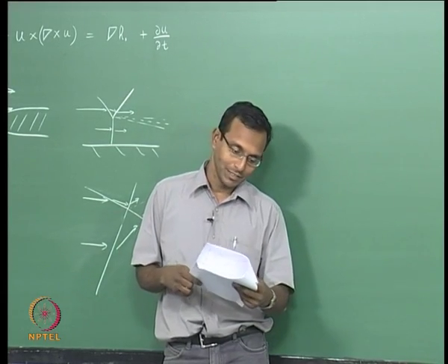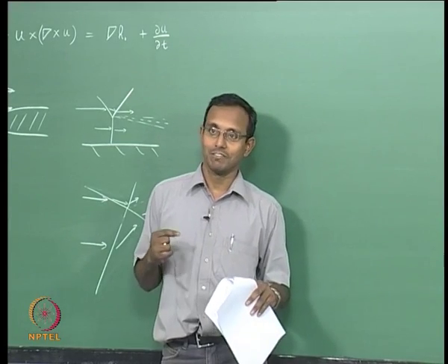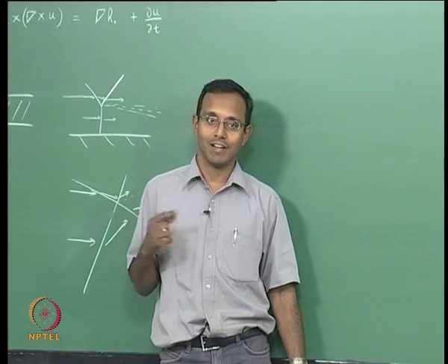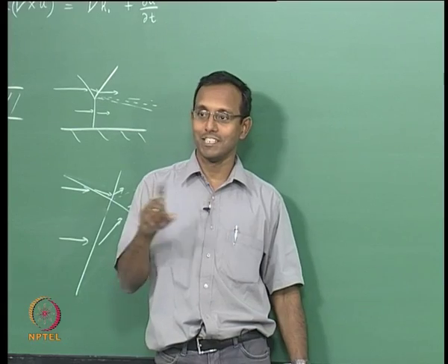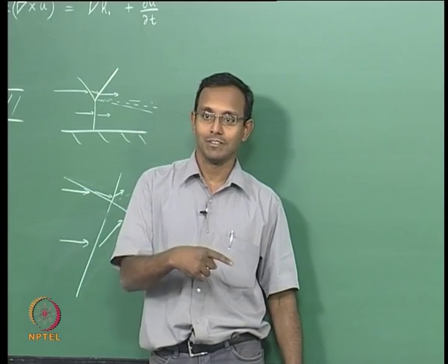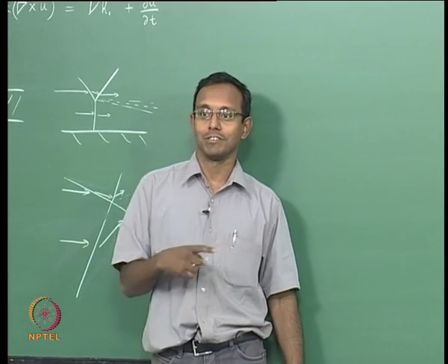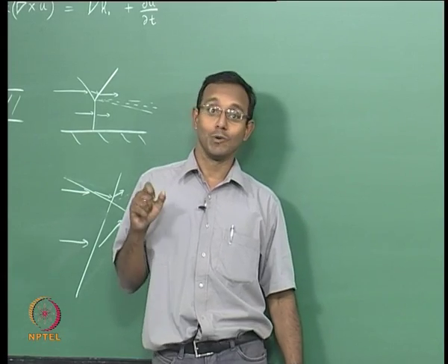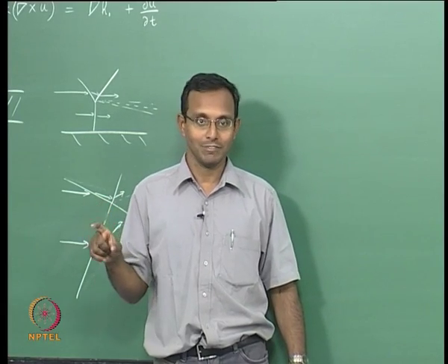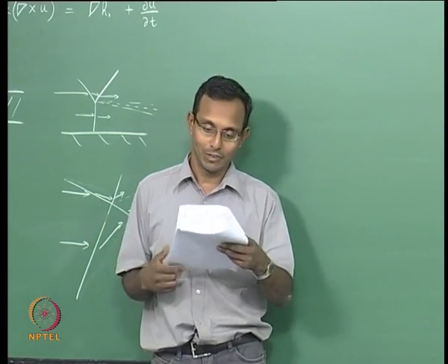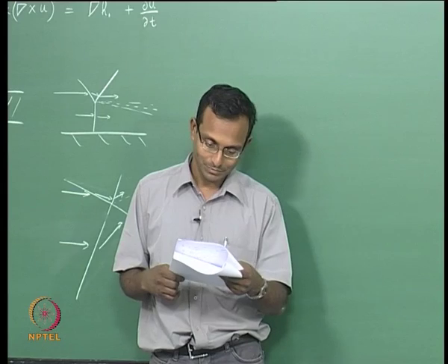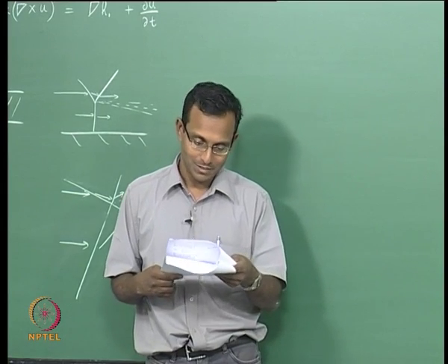That is one thing, and this is one problem where we are going to say viscosity is present. The only other problem where we discussed viscosity was the shear layer. After that, it is this one. In the middle, we discussed the energy equation, and we know that because there is viscosity present, we may have entropy production, and because there is heat transfer, there may be entropy production. Now we said adiabatic, so there is no heat transfer into the gas. So there is only one way of producing entropy, that is viscous forces. That is all you are going to have currently. That is coming from our discussion on the energy equation and entropy equation, which was already done last class.